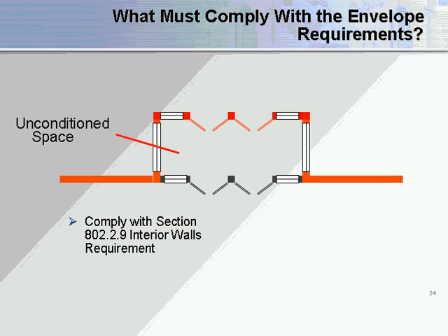What happens if our vestibule pokes inside the building? Well, again, this is a very common consideration in a lot of vestibule requirements, especially in areas where by code and by regulation, you cannot put a vestibule off the front of the building. So it would have to actually stick inside the building. In this case, we have our conditioned space in the area where I've just put the yellow circle. Outside the building is right here. We have our unconditioned space, again, formed by the vestibule. So our vestibule area where the red goes around actually forms the unconditioned space.